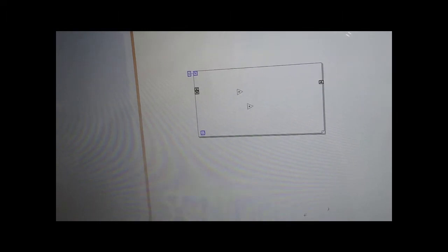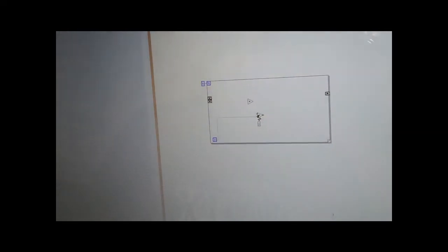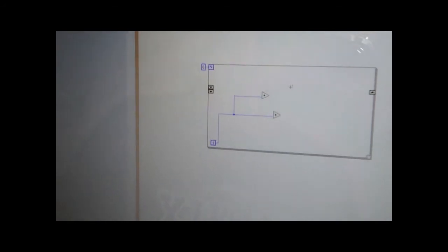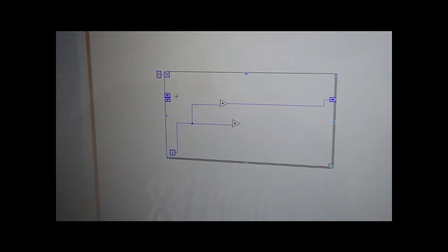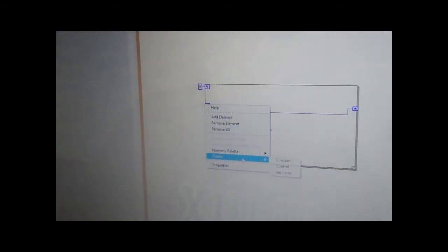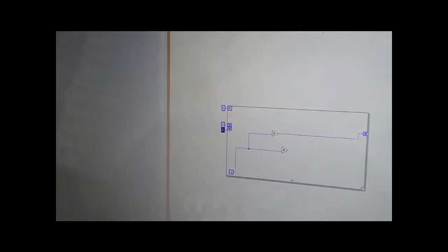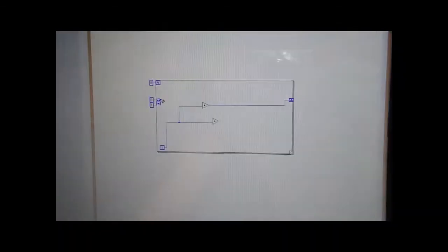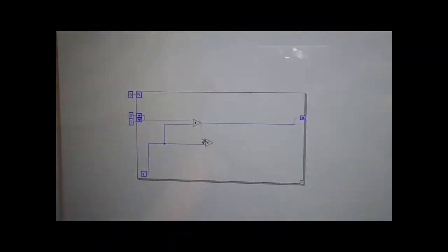And then we need to connect the first one and the second one both to I. So we bring I over to the first one and to the second one. Then you connect the first one to the shift register here, and then that defines the shift register. So now we can go in and do a create constant of 0 for the first one and 1 for the second one. Now let's run our first shift register over to our first addition and our second one over to our second addition.